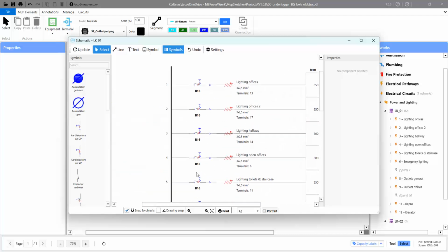All right, then on the left we have our circuit breakers. So you can select them and you can see that it is called a symbol. At the properties, you can rotate it, you can change the size, you can change the label. So if this has to be a C20, you can just change it and it will update. And you can also change the symbol by clicking on the change image button. And if you do that, then you can pick any of the other symbols that are on the left and it will swap it out with that symbol.